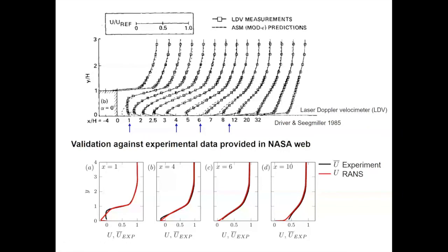And so when you look here, these are comparison between a numerical model, including a sophisticated turbulence model and the LDV measurements. And we first compared our URANS, which was based on a Spalart-Allmaras model. And we saw reasonable agreement, of course, not in this very delicate region here, where agreement between different turbulent numerical simulations and measurements was actually never really achieved.